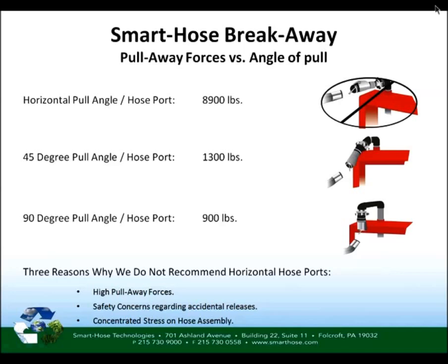Hello there again. This is our breakaway. I know the webcam makes it kind of hard to show, but this is a cutaway view of our breakaway here. This is our end fitting, and then you have your ferrule attached to the hose. In a horizontal port connection, what you're actually measuring is the tensile strength of our breakaway. This is the component that holds the end fitting and the hose. And you can see the groove right down the middle. That is our engineered break point.